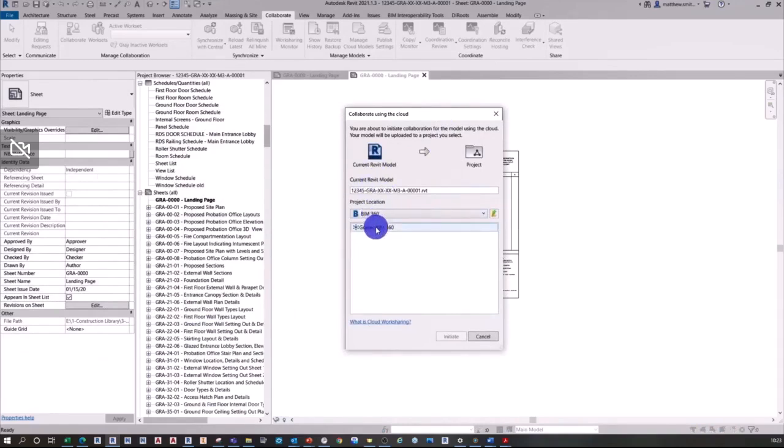But obviously, because we have the Collaborate Pro subscription, I am now collaborating within the cloud, and here I have a selection of the projects that I'm involved in, of which we can pick and choose which projects we want to access. From there we can then access the folder structure that is available within our project, and so now I am collaborating my model into my work in progress area using the current ISO 19650 file naming convention.